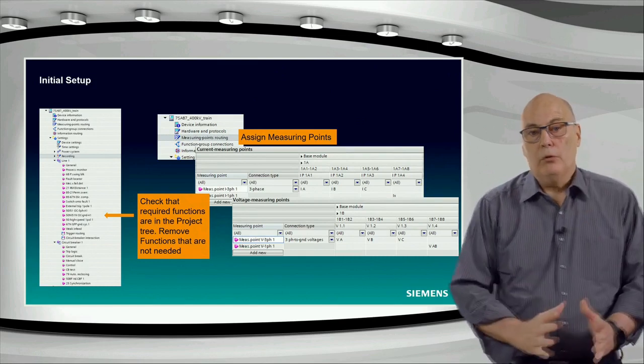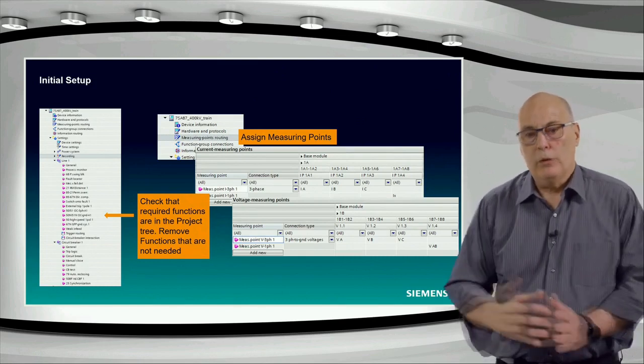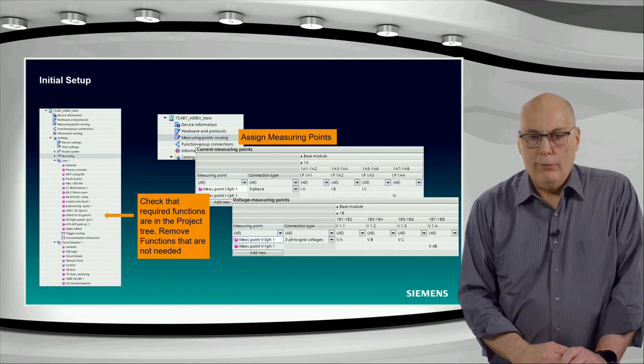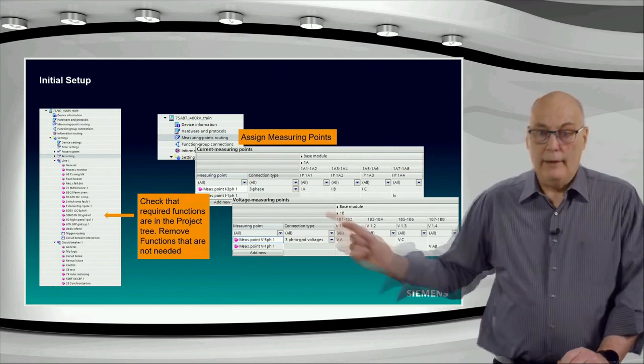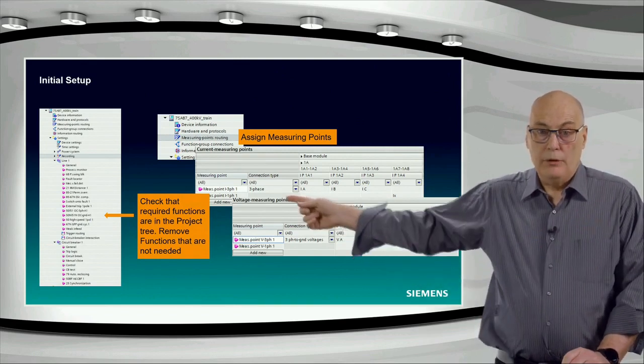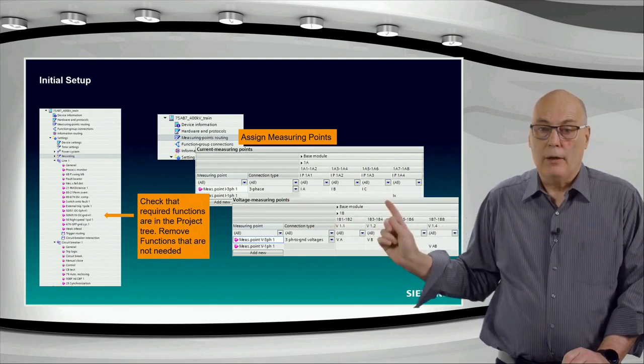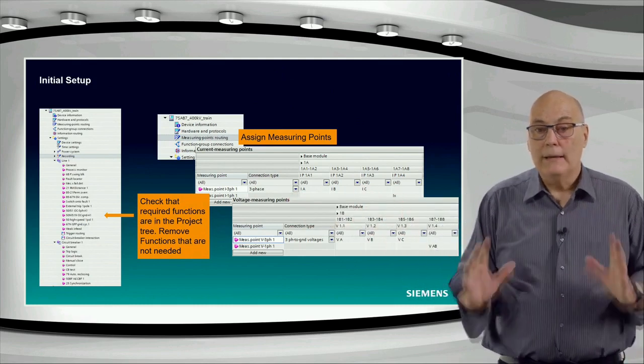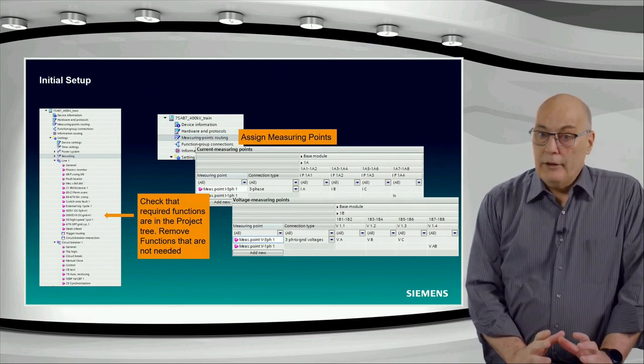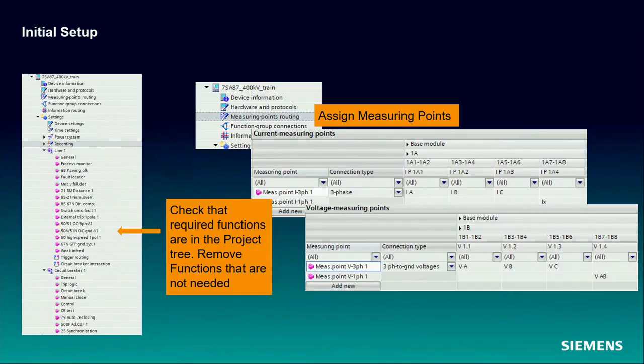So if we're going to apply the parallel line compensation, we also have to measure the ground fault or residual current from the parallel line. That's what the second measuring point is for, a single-phase current measuring point, applied here at the moment just as IX. You don't know yet that it's a parallel line. It is just a measuring point at this point. It is nothing more than that, right?